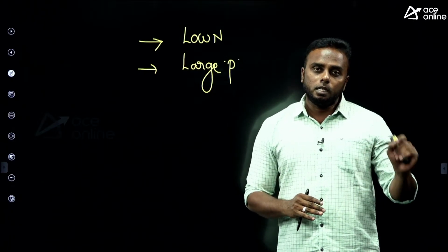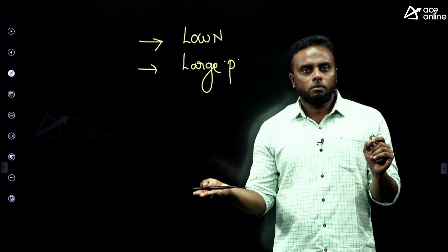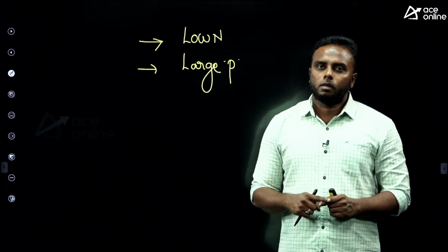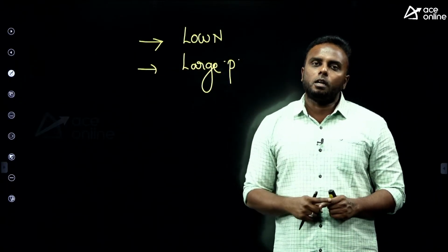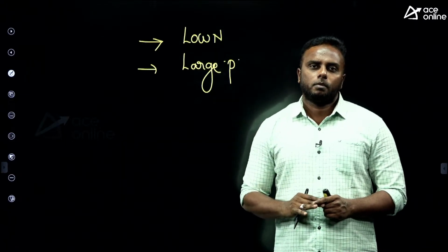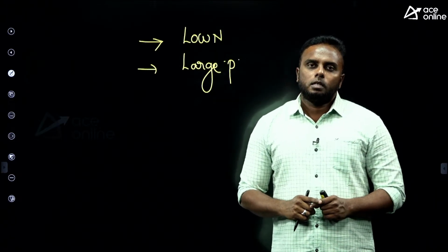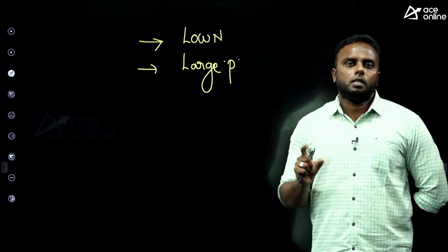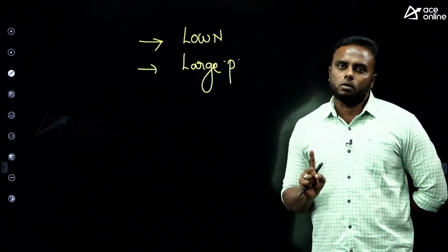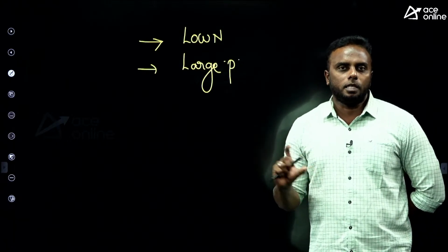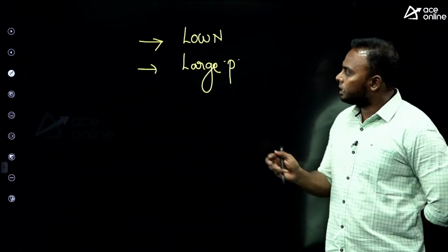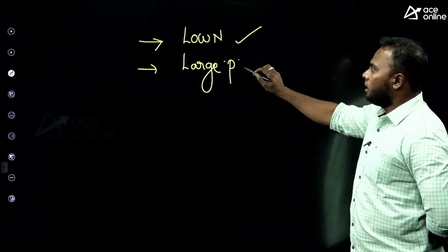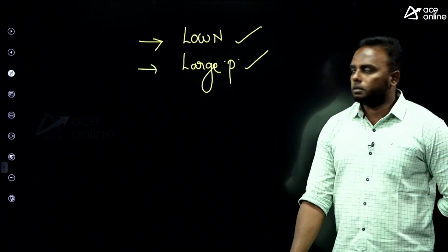Now what is that 30 RPM in 300 RPM? It is 10%. But previously for 1500 RPM, that 30 is negligible, but not negligible here. That's why in low speed, whenever we require a constant speed, the induction motor is not preferred because it cannot maintain constant speed. It is variable here.